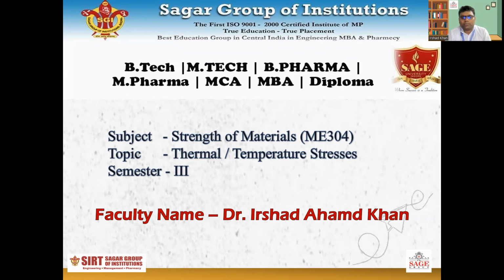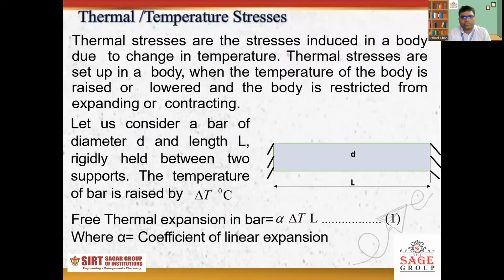Let's come to the topic, thermal or temperature stresses. Thermal stresses are stresses induced in the body simply due to change in temperature. They are set up in the body when the temperature of the body is raised or lowered and the body is restricted by some external means from either expanding or contracting.